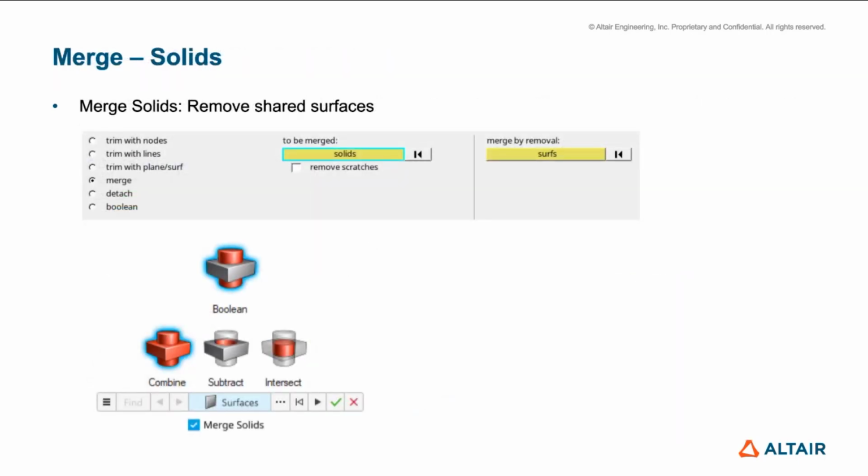This request also came from field, and this is to enable the merging of the solid. So we had merged solids by removing a surface. For example, if you have a solid which has been split into two and you have a shared surface, all you really care about is deleting that shared surface. This may not be a very time consuming Boolean operation.